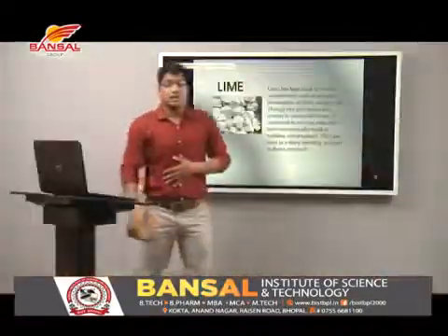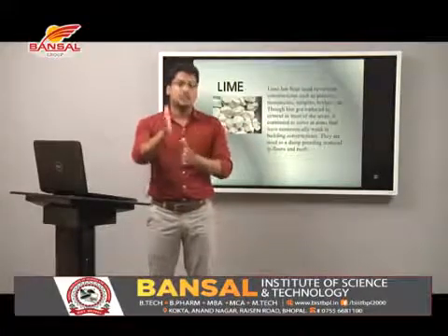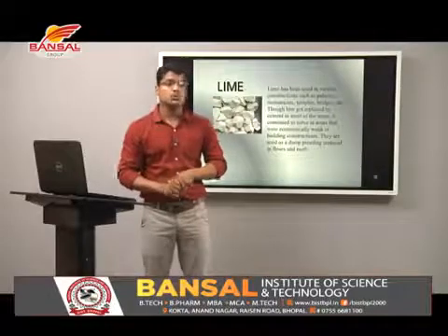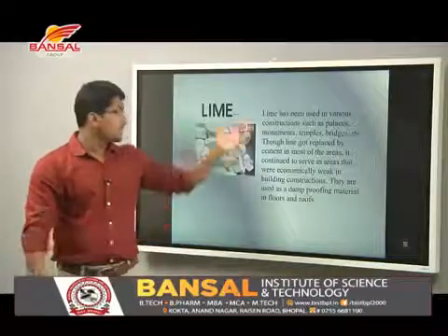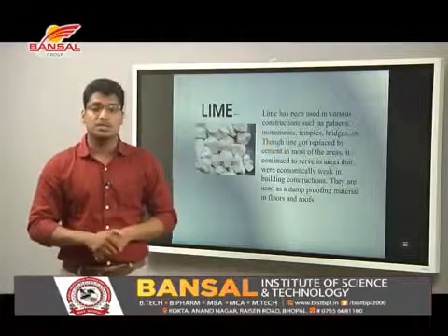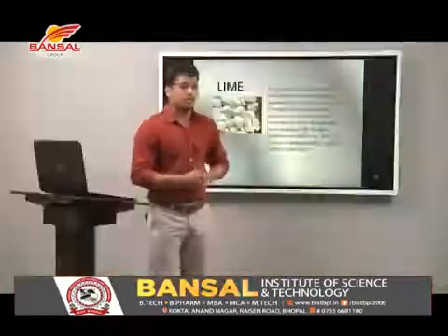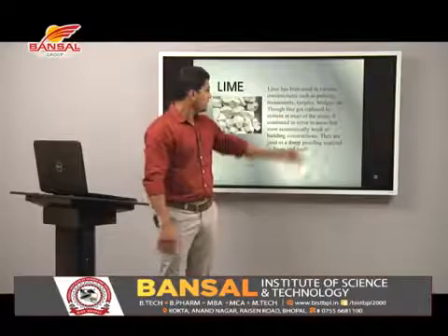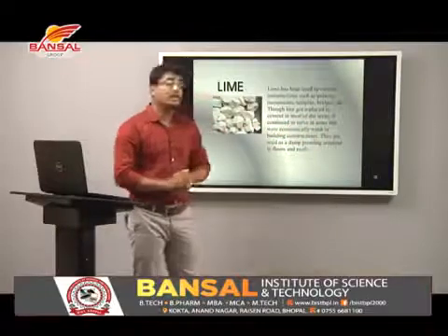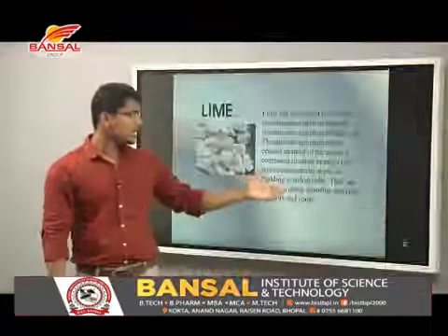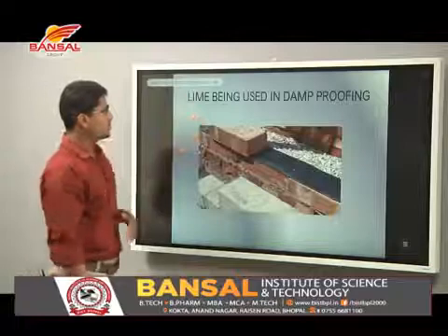Now, lime. Because of its benefits, lime was nicknamed nature's cement. It is mostly used in various constructions such as palaces, monuments, temples, bridges, etc. Though lime got replaced by cement in most areas, it continued to serve in areas that were economically weak in building constructions. It is used as a damp proofing material in floors and roofs.